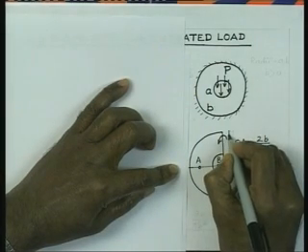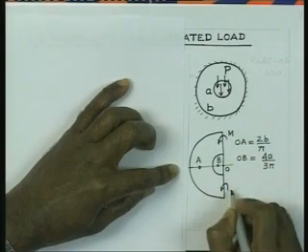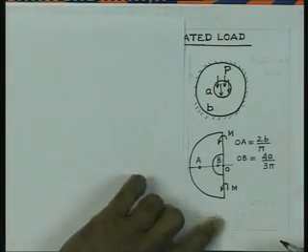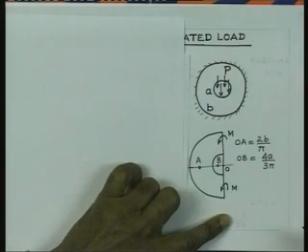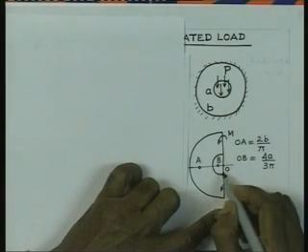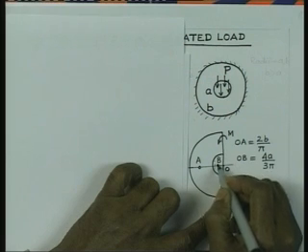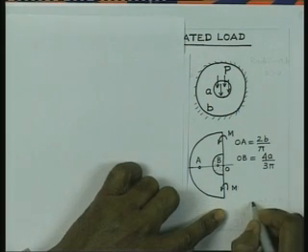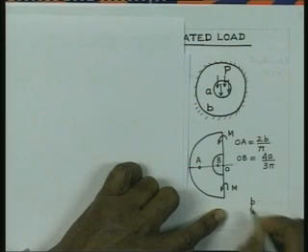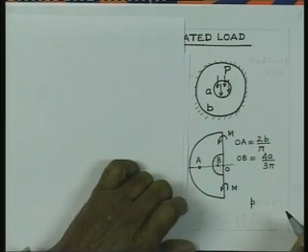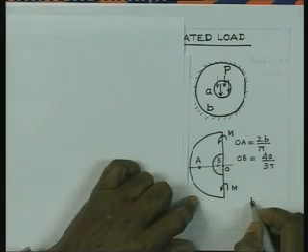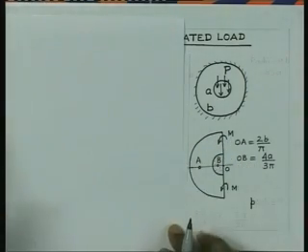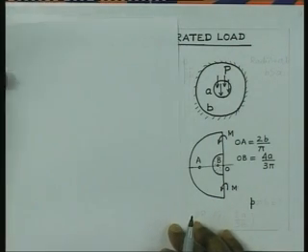This intensity of bending moment, let us represent it by M everywhere. The loading which is uniformly distributed over this small circle, the intensity of this loading, let us just say P, sorry, I am sorry about that. Let us consider that the reaction force which is all over this boundary is equal to R per unit length.